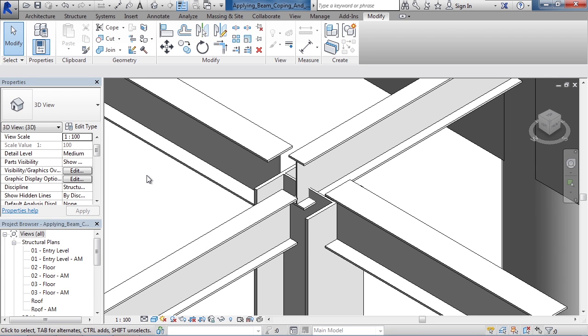To view or change that notch spacing, we first select the beam that was notched, then look for a property in the property area on the left that controls the actual cope. We can increase or decrease that value, which increases or decreases that cut area. To remove the notch, on the Modify tool, again on the Geometry panel, there's a Cope Removal tool. Selecting the beam first, then the column that did the cutting, will remove the notch from the beam.